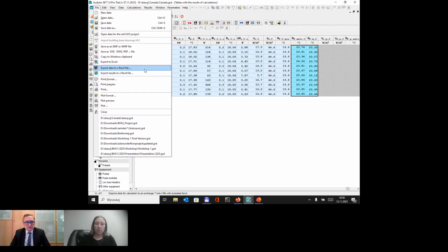But you can already export it at this stage. With export of results, it exports a part of the graphical 3D model, also the properties of all the elements, and also the result of calculations like heating power, water velocity, selected diameter, and so on and so on.